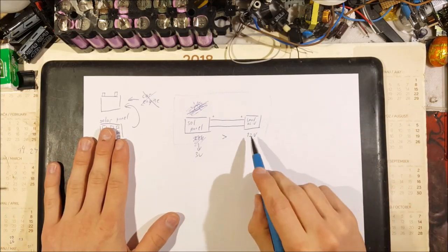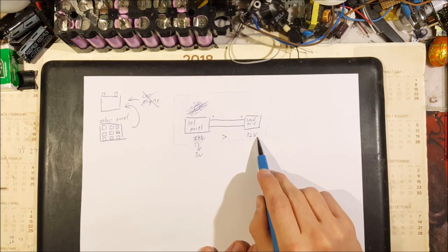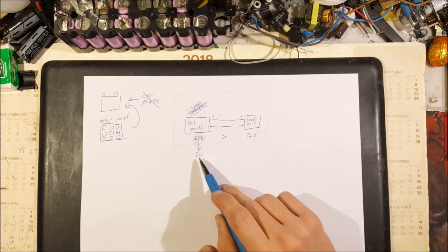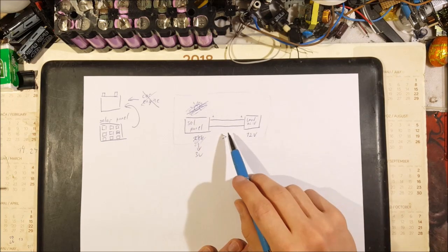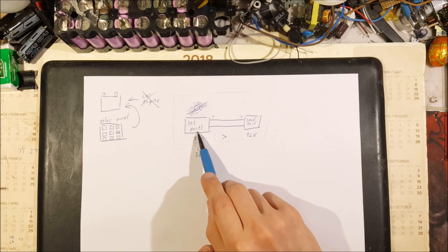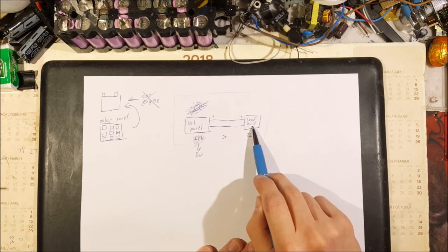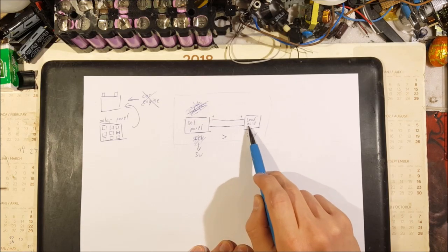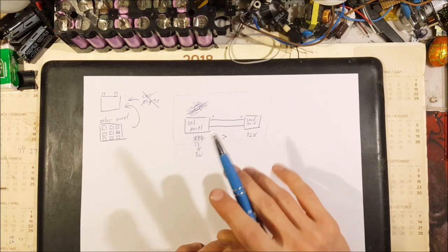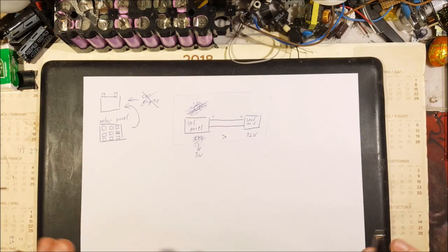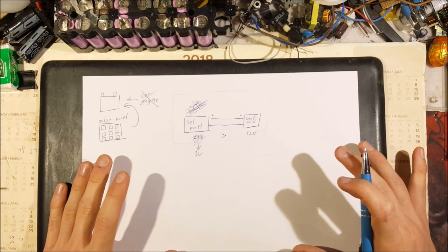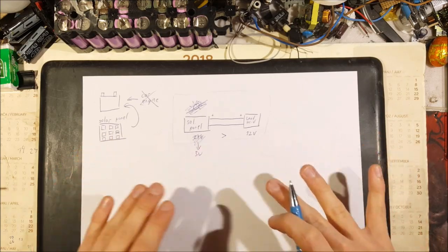Now we have a lead acid battery whose voltage is way higher than the solar panel, meaning that now instead of the solar panel charging our battery, our battery will dump a whole lot of current into our solar panel, thus destroying it. Now we don't actually want that, so let's think about it, what would be the simplest solution to stop this from happening?